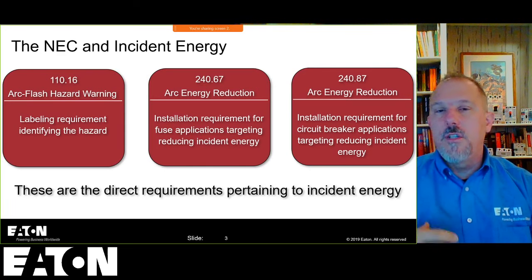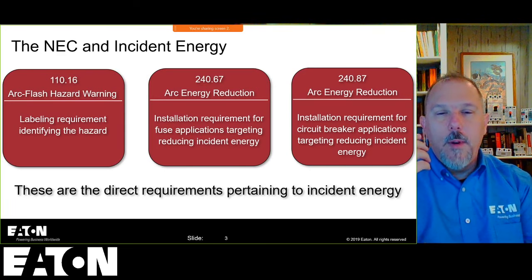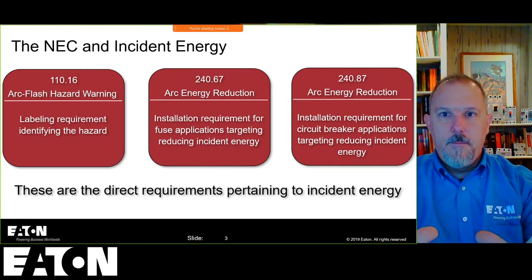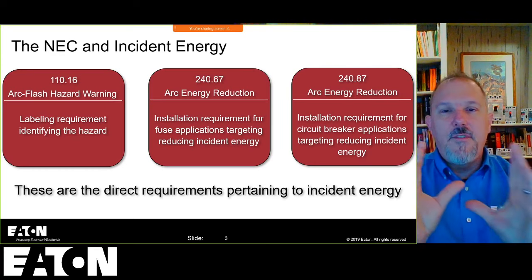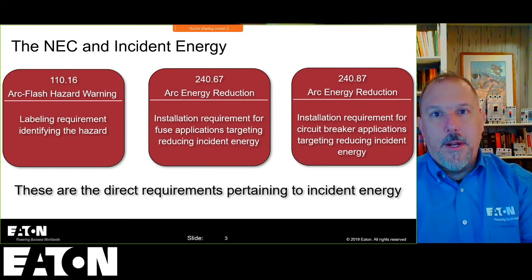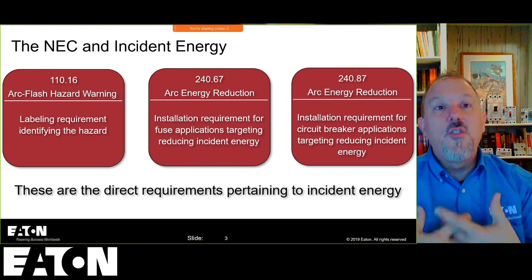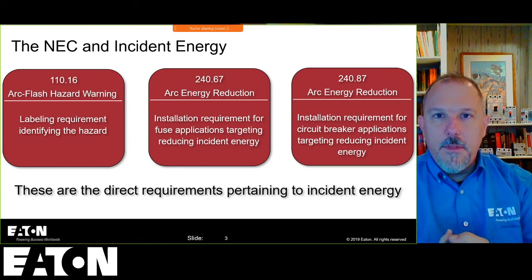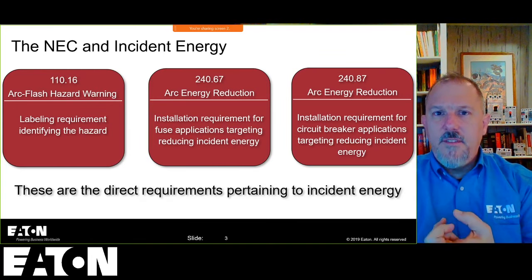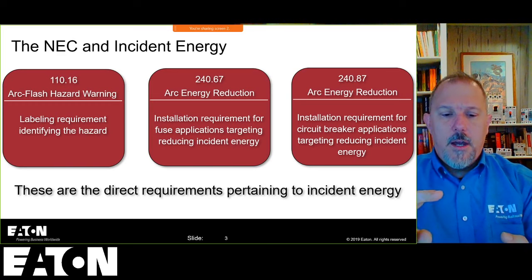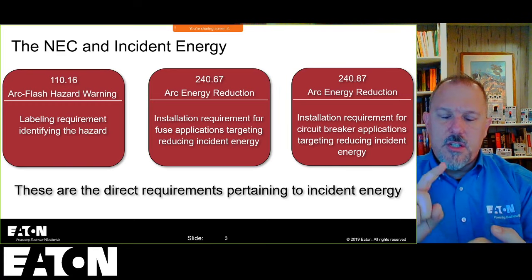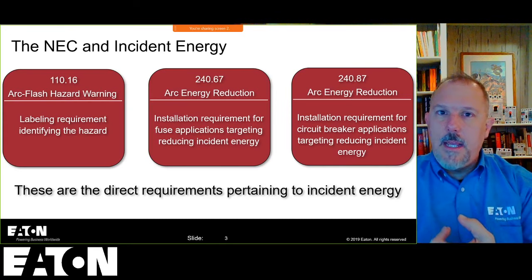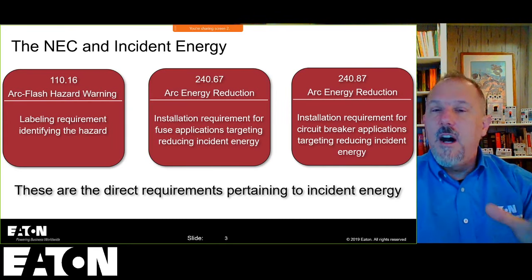So electronics was progressing, and we were able to put electronics inside of relay type enclosures. And then we were able to make that even smaller and get it into these big power breakers. And we were able to provide ground fault protection of equipment. And if you look at the dialogue, the panel, the public inputs, in the 70 code and the year prior, there was a lot of discussion and debate about service entrance equipment burn downs, as they called them, and they had pictures of arc flash events. IEEE had a lot of papers in that time period on these arc flash events.